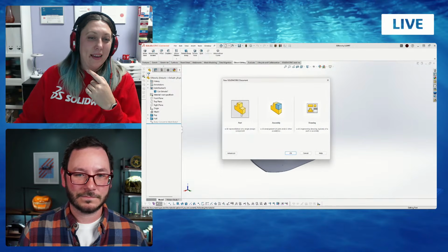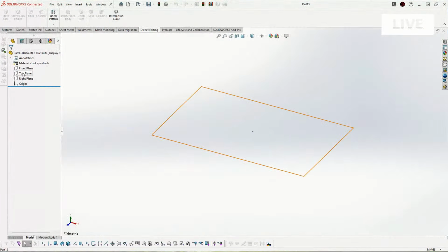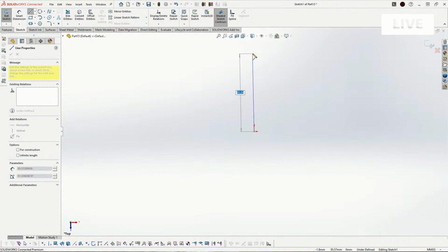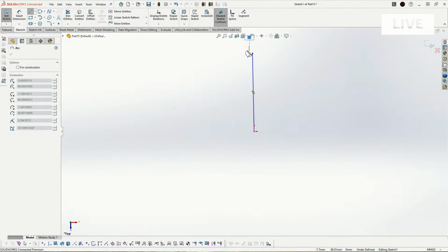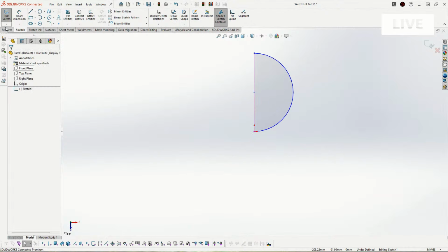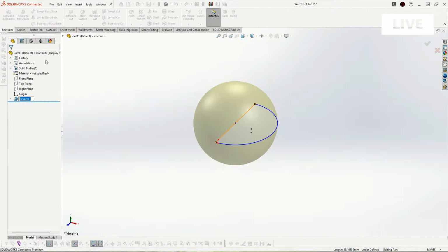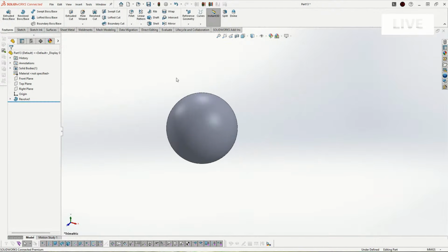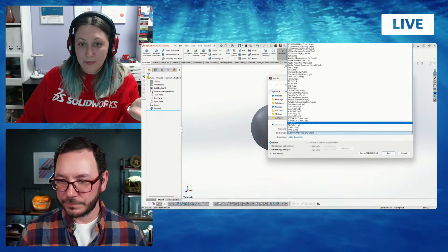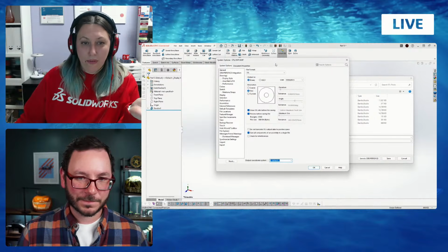So if you make, I will use maybe again a sphere, because on the sphere you can see really well polygons. So you can go in both directions. When you go save as STL first, you can go to the options and make it really rough and choppy.